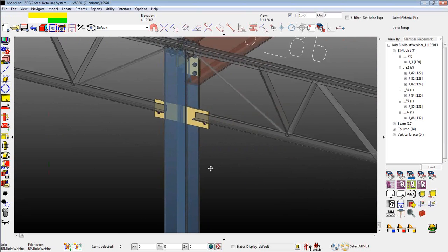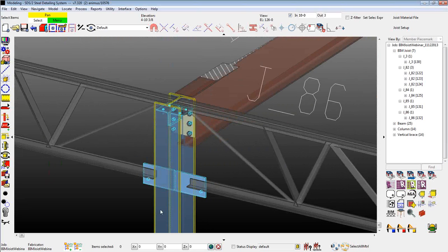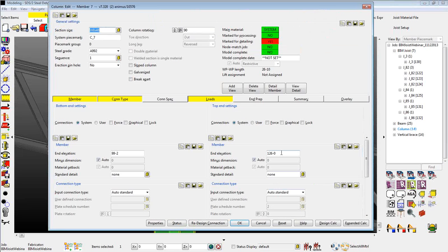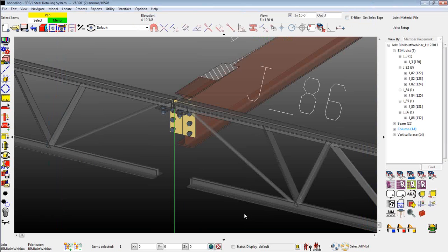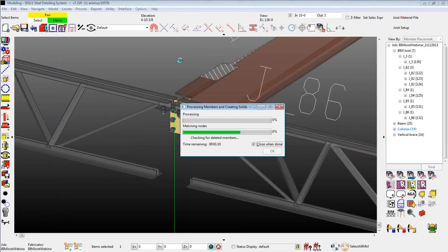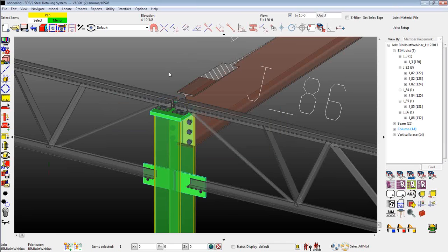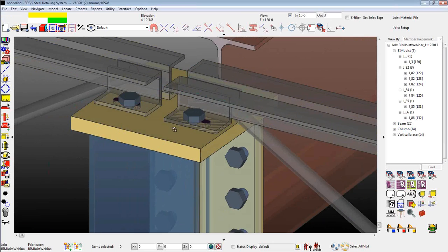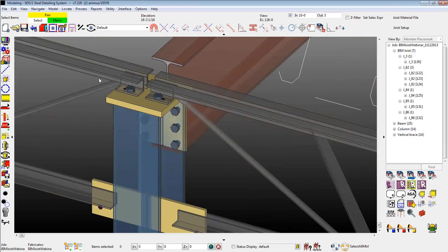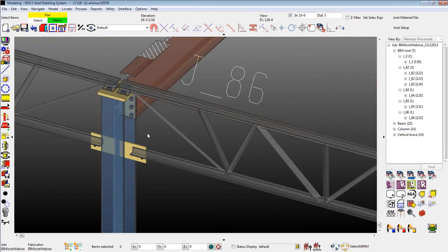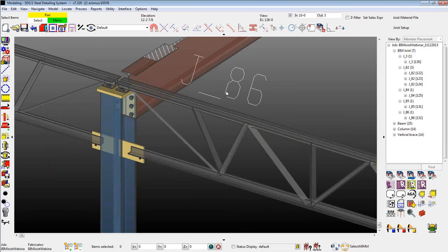And just to take that cap plate one step further, I'm going to go down here to where we have two joists framing to our column. If I drop that down the 2 1/2 inches and apply my plate from the schedule again, it should give me connections for both of those joists then. Okay, and we can see that.